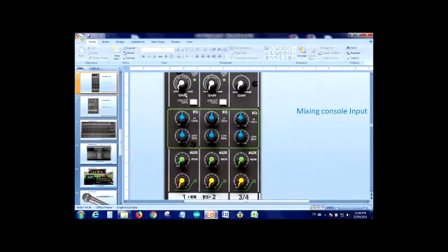Mixers are supposed to be versatile. Anything should be able to plug in any kind of signal. That's what makes a professional stage mixer. And now over here you have a little button that says low cut. Usually below 80 hertz is the threshold. What that is: